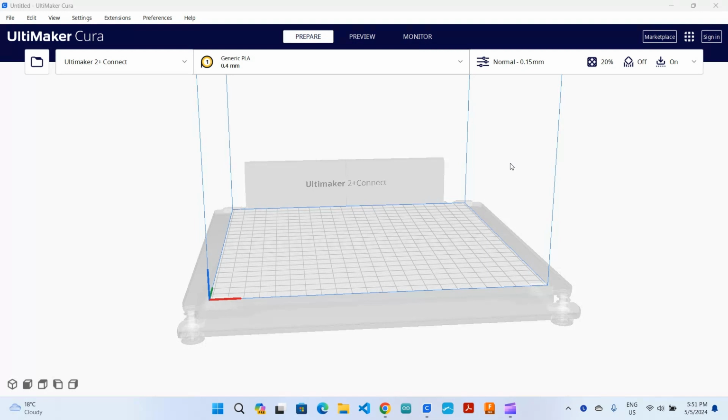Before you can start 3D printing, you need to slice your 3D object. This basically converts the 3D mesh, which defines the edges and faces of your object, into a set of instructions for the 3D printer, telling it how to move the motors at what times. To do this, you'll need a slicing software.